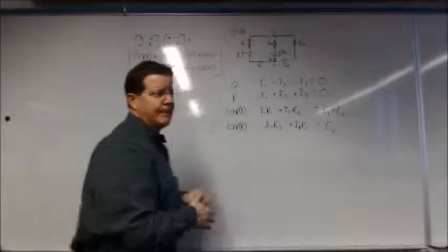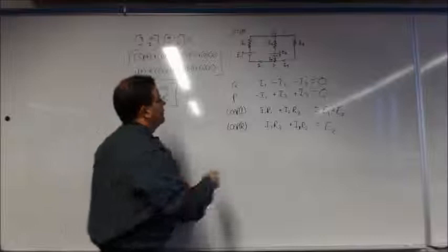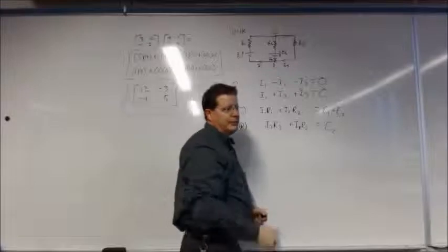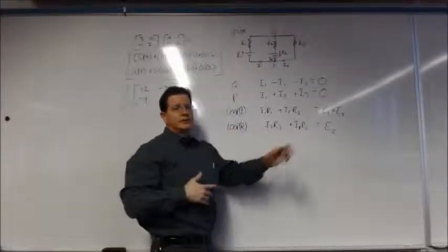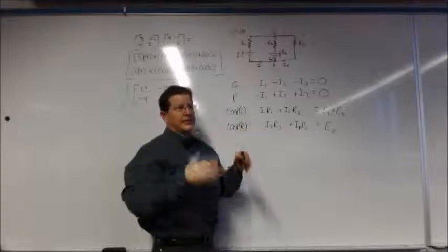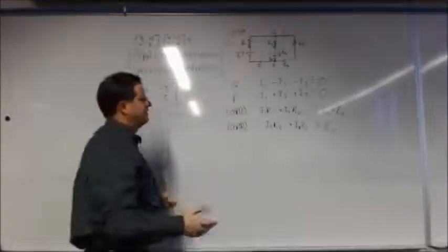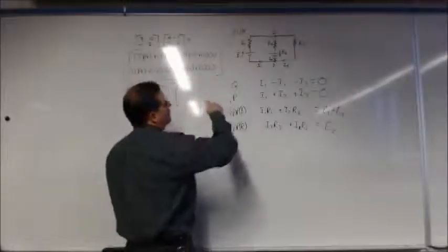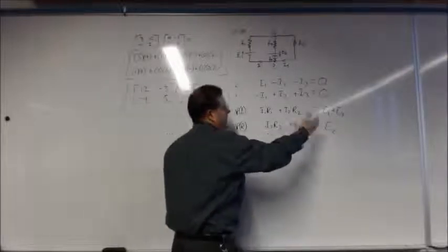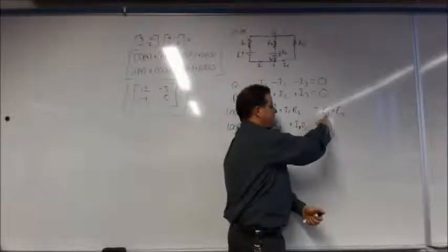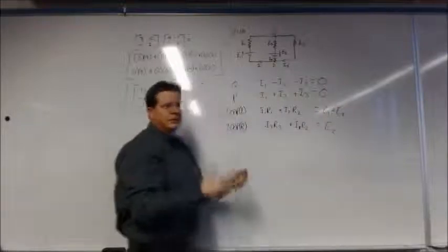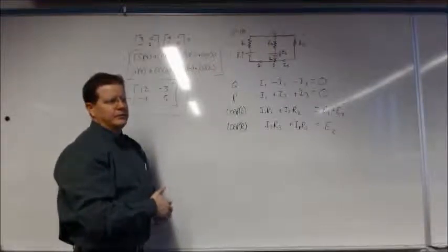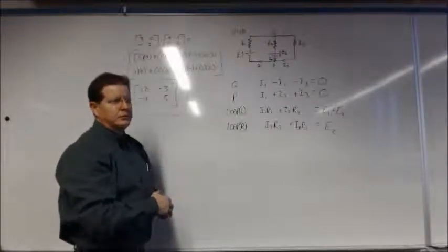Can you just quickly go through the sign convention, how you got negative or positive? So for the nodes, if we're going in, we're saying that's positive. If we're going out, we're saying it's negative. You can say it the other way, it doesn't matter, just as long as you're consistent with all your nodes. It's just a convention. What about the E's, the batteries? Well, if I had numbers, this would be, whatever, 90 volts plus 40 volts, or 5 volts plus 2 volts, or whatever number that we're using. You don't have negative voltage, so at least I don't think so.